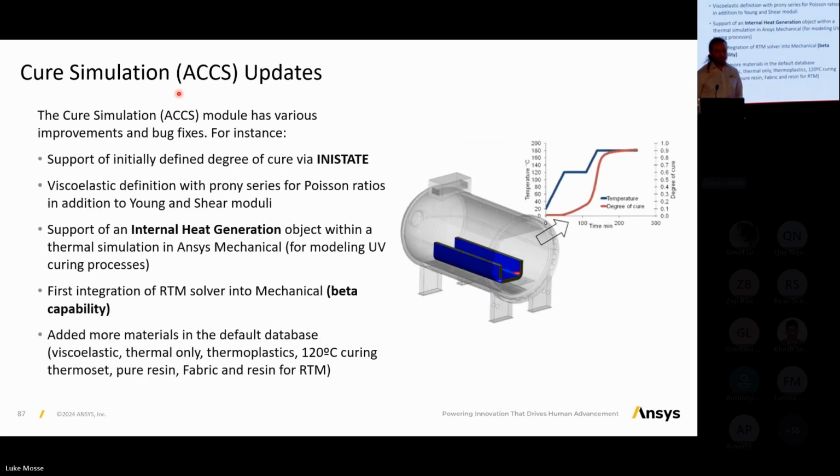And then the composite cure simulation. So Ansys composite cure simulation is for simulating spring-in effects as the composite cures in the autoclave. So it calculates the shrinkage due to thermal and chemical effects. And you basically give it the whole thermal chemical profile with the history of the curing, and it predicts the shape deformation of the composite due to the resin